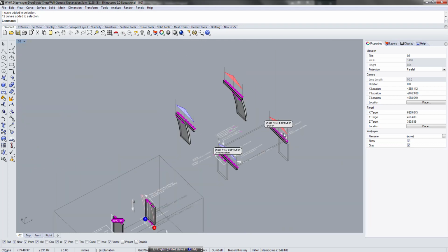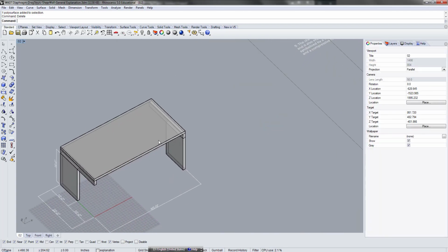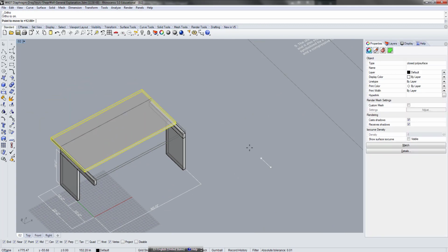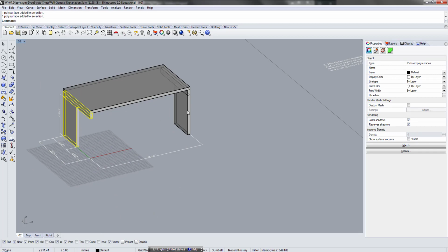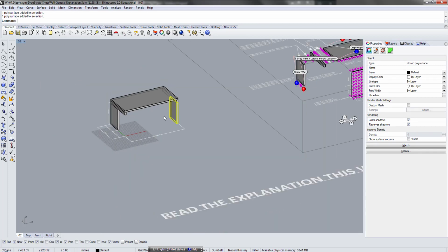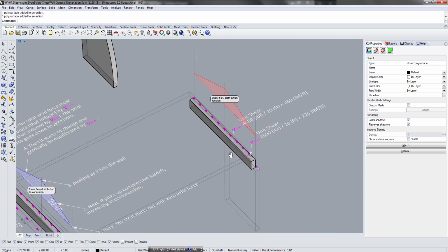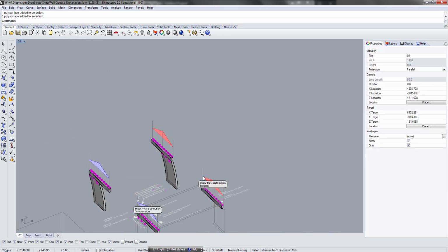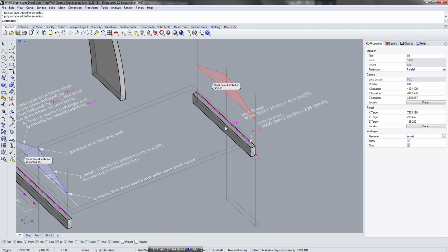If you look at the other side, remember how these two walls are located differently. I have this diaphragm going in this direction, but on the left side I have the shear wall at the far end. On the right side I have the shear wall at the beginning. So in this case the story is a little bit different in terms of the behavior of the drag strut. What happens now is you have a wall and you have this beam, and this beam is being pushed in this direction throughout.